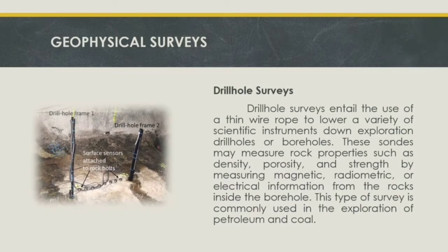Drill hole surveys. Drill hole surveys entail the use of a thin wire rope to lower a variety of scientific instruments down exploration drill holes or boreholes. These sondas may measure rock properties such as density, porosity, and strength by measuring magnetic, radiometric, or electrical information from the rocks inside the borehole. This type of survey is commonly used in the exploration of petroleum and coal.